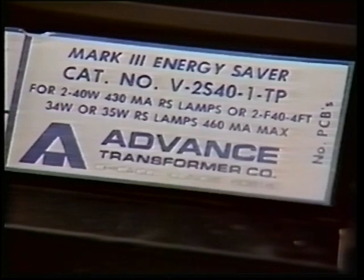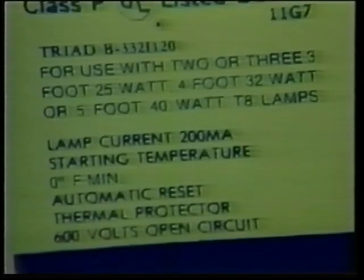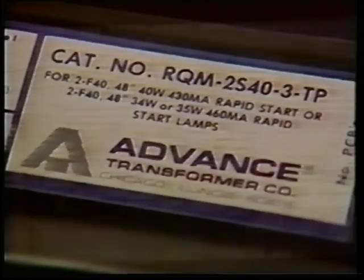The increased awareness of energy consumption has led to the introduction of more energy-efficient ballasts. These are designed to save electricity by reducing losses within the ballast. Used in conjunction with energy-saving lamps, these ballasts can result in significant savings. The most energy-efficient ballasts are the electronic ballasts. These ballasts operate the lamp at higher frequencies than magnetic ballasts. They not only save energy, but they also improve lamp efficiency.